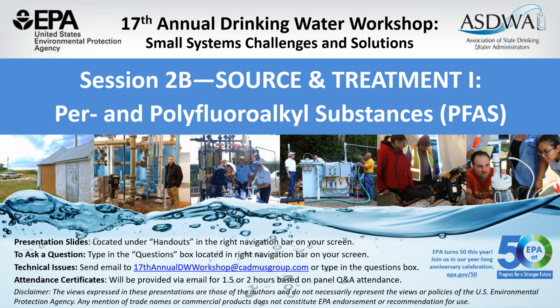For your system, how was the spent GAC handled? So the spent GAC for this specific system, the specific manufacturer has that undercone design so that it makes it easier to flush out the carbon. That carbon was then taken to a reprocessing facility. So it was going to be recycled, or at least the potential for it to be recycled was going to be reserved. The health department is still, I don't know that we've finalized a policy on the use of recycled carbon. So I know certainly at the time of the change outs we had not, but this facility was sending that carbon to be regenerated, and then it was going to be stored pending a policy decision.